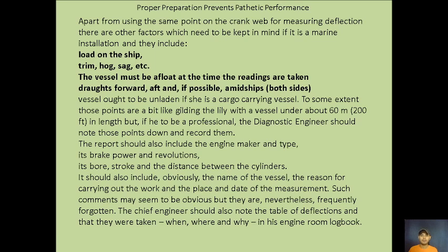Proper preparation prevents poor performance. Apart from using the same point on the crank web for measuring deflection, there are other factors which need to be kept in mind if it is a marine installation. They include load on the ship, trim, hog, sag, etc. The vessel must be afloat at the time the readings are taken. Draughts forward, aft, and if possible, amidships, both sides. The vessel ought to be unladen if she is a cargo carrying vessel. So there are different things that you should consider in doing your crankshaft deflection.